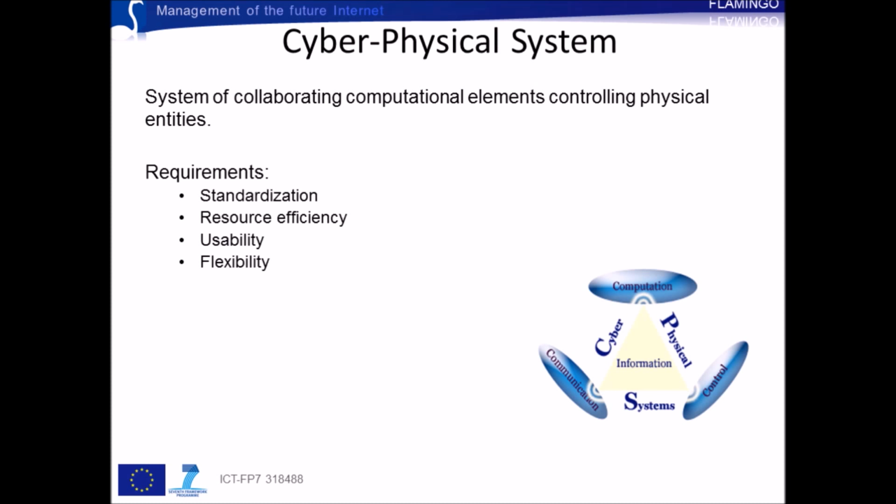This central unit compares the received value with a set one, and depending on the result, an action is planned and executed. If the room temperature is below 23 degrees, the heating control is activated and windows are closed, if the setting says it should be warmer. The measurement is repeated periodically, so that a cycle of actions takes place, which is illustrated in the figure on this slide in the right corner of it.